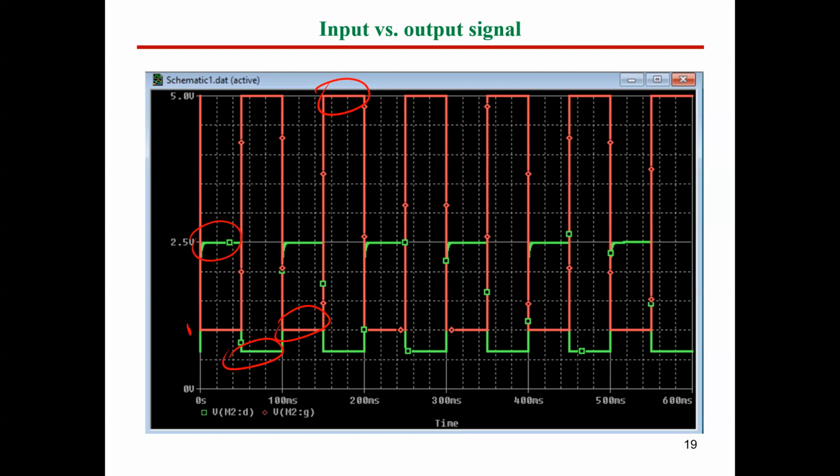One note, when you make any kind of application for drivers like that, it's better to use very well-known values for active low and active high. For instance, if your circuit biasing volt VDD is 5 volt, try to keep the active high volt very close to the 5 volt.